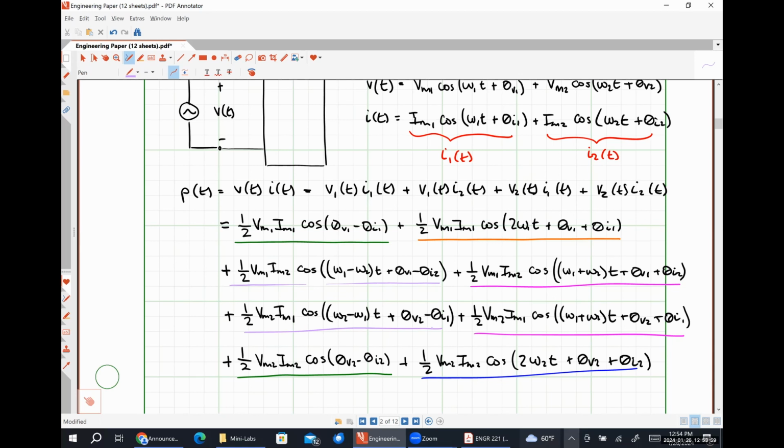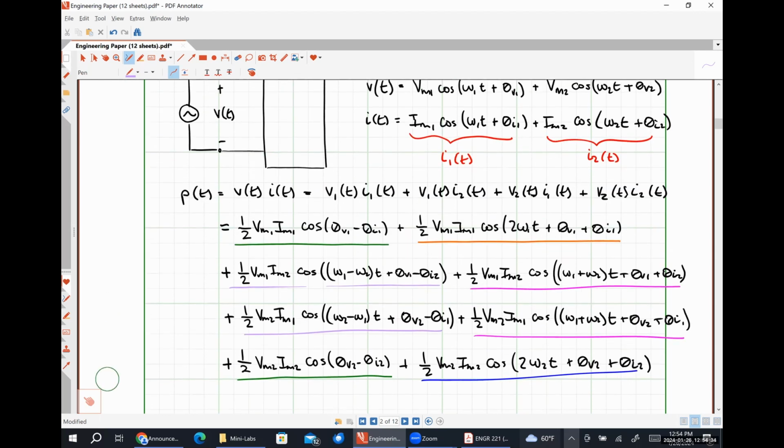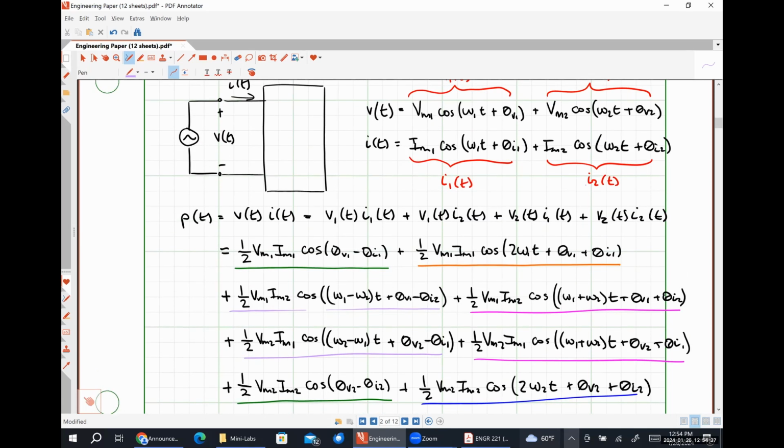Okay? So this conundrum right here is actually one of the main reasons why effective values were developed. The math is tedious when we're at 1 frequency, but at multiple frequencies, it becomes terrifying to figure out what's going on. So let's figure out how to determine the effective value of a multi-frequency circuit, right? So realistically, I would wind up integrating this thing over the period of whatever our voltage waveform is, which is the same as the period of our current waveform.